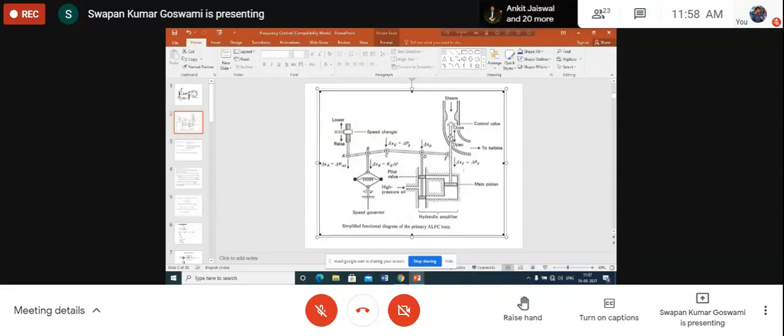Now, along with this main piston rod, we have a rigid link CDE, pivoted at D. Here it is connected with the main piston rod at E. Another rigid link is there, ABC, pivoted at B. At B, we have this rod connected to the speed governor mechanism, and the speed governing mechanism is the heart of this total frequency control process.